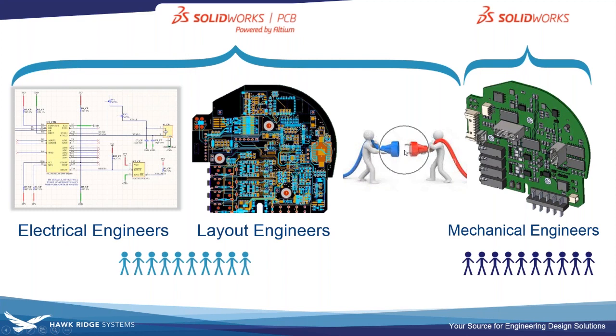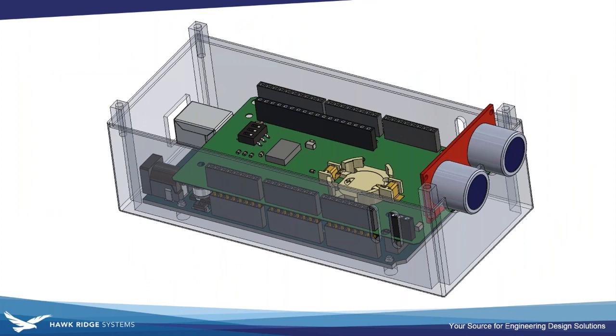The product includes real-time collaboration. So it's essentially pushing and pulling files to and from SolidWorks. Once you're in the SolidWorks environment, you're going to have a three-dimensional model of your printed circuit board with editing capabilities for component placement, board outline adjustments, mounting hole mechanism adjustments. And then you simply push that back to the SolidWorks PCB tool, and you will visualize real-time updated edits. Okay?